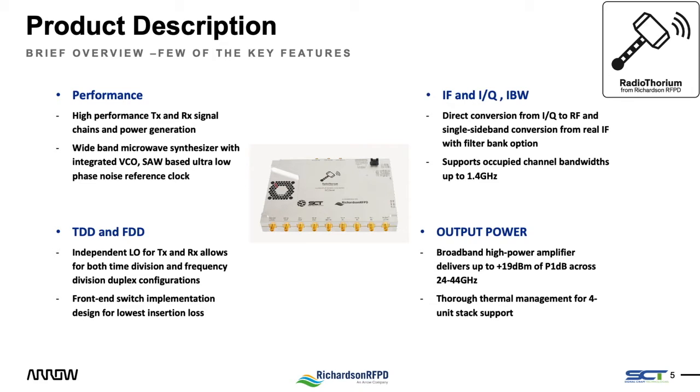The IF TX-RX are single-ended ports, although the frequency range of the up and down converter chips we used in our design should cover 0.8 to 6 GHz for RF inputs. The broadband 90-degree hybrid we use in our circuit limits that range to 2 to 6 GHz. On the baseband I/Q ports, filtering should be provided externally if the requirements for channel bandwidth are lower than 1.4 GHz.